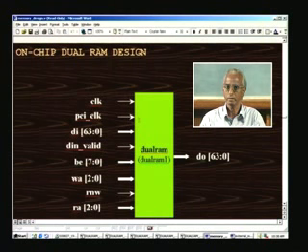I mean, a different block of image will be filled into RAM 2, and when this happens, concurrently we will be reading from RAM 1, which was filled earlier, and then process DCT-Q from that block of image. That is, the first block of image will be processed while the second block of image is being concurrently loaded into this RAM, and that is how the requirement arose here.